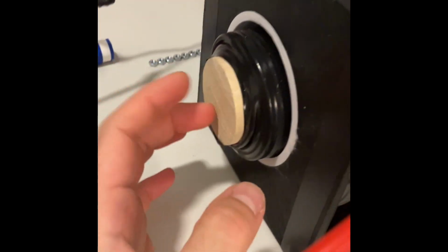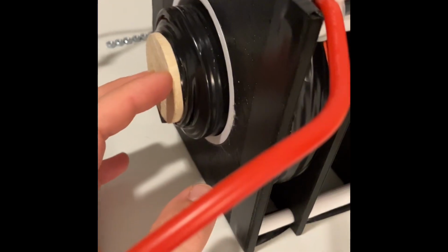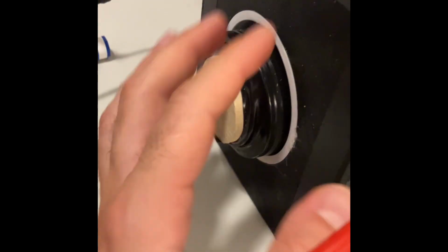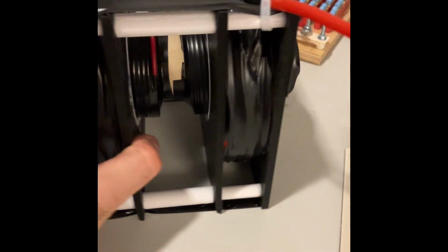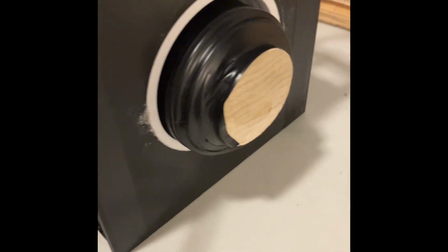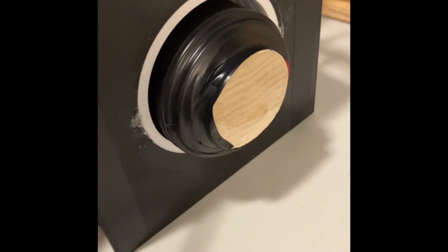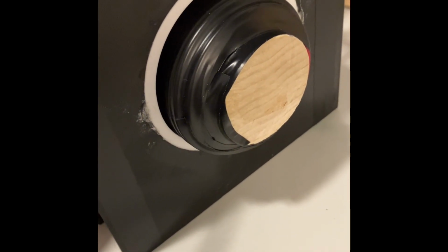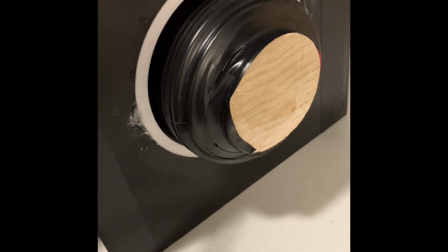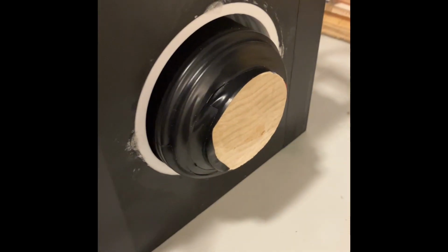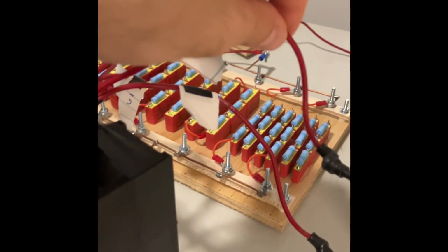We just have this wooden spool in the middle, like he says in his lecture, and then PLA plastic from a 3D printer. So in the middle here we have our primary winding. It is a wooden spool with 4 layers of 14 gauge stranded copper wire. So it's just this sort of stuff.